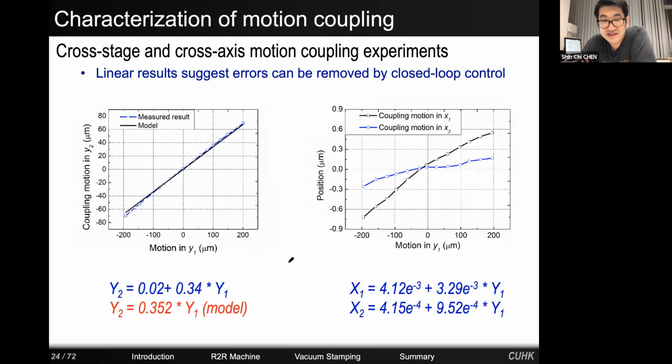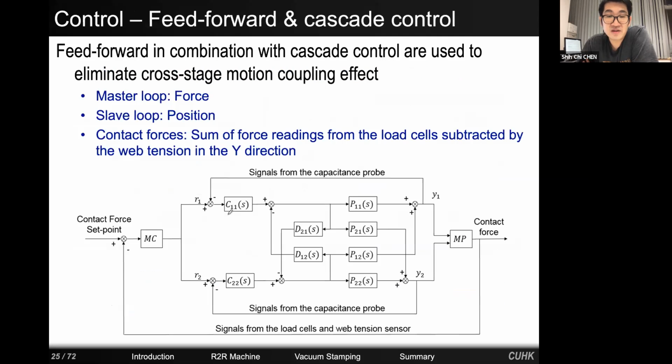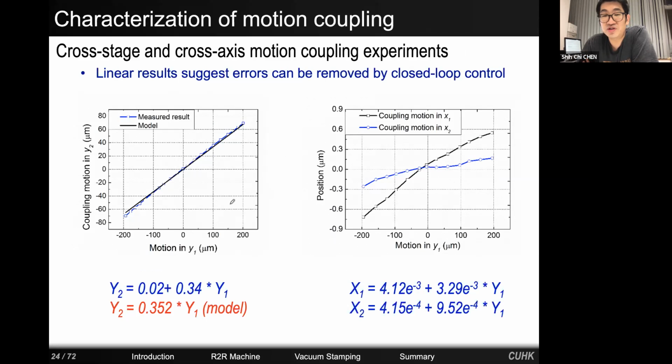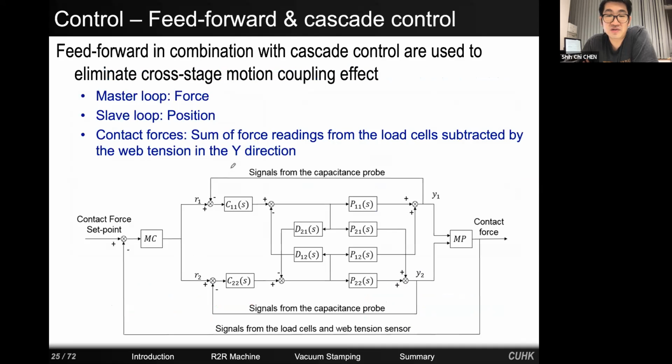And as I said, flexures are the mechanism that has the highest repeatability. It will have errors in terms of positioning, but these errors are repeatable. The error sources are from fabrication errors. So we can measure these parasitic errors and apply them in the control system to eliminate these errors, which are within hundreds of nanometers range.